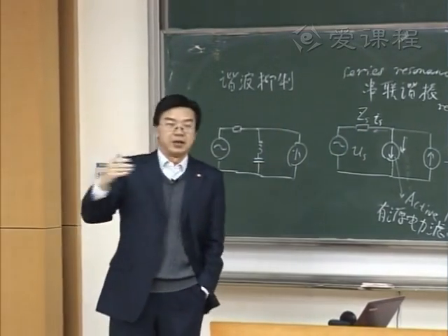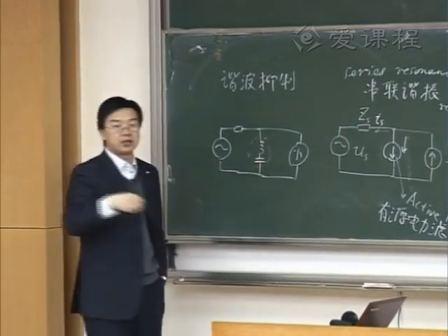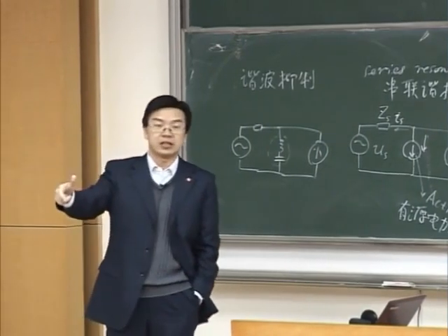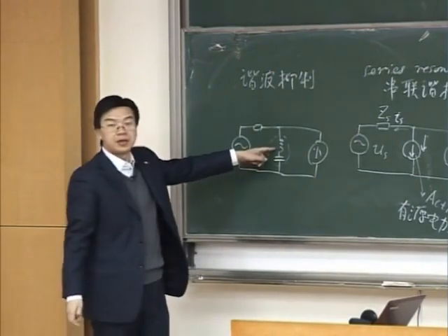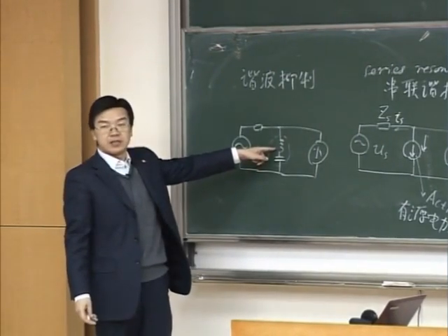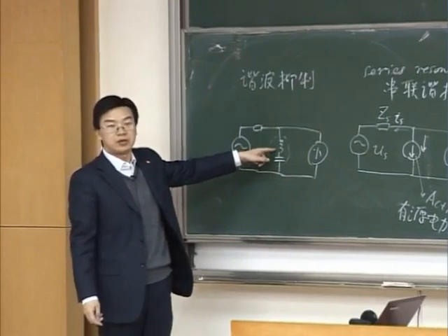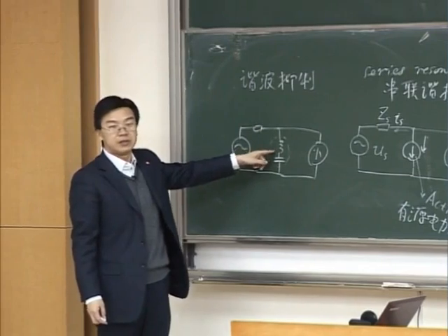But the values of the inductor and capacitors are fixed. Once you design it, then you install it, and those are fixed. So those can only be effective at the resonant frequency harmonics. Those frequencies are fixed.